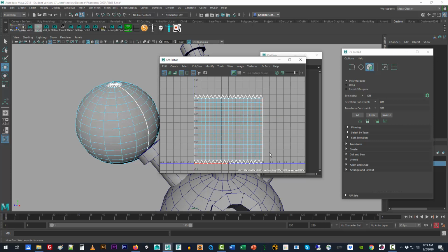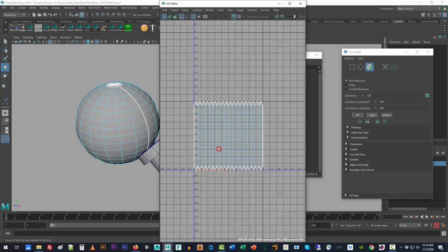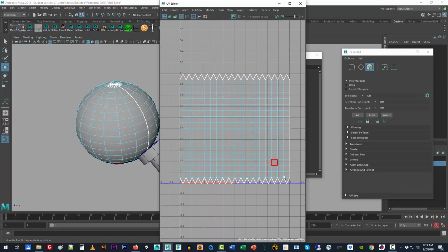One of them is whether or not we have the sphere laid out like a flat map, which is sort of the default of Maya, or whether we can take these spheres and actually make them into sort of orange slices in the UV sets to reflect the actual mass of how these are laid out. So the way that we do that is we tell Maya, first of all, we'd like to cut things because it needs to know if it's going to squeeze them in at the hemisphere, exactly where those cuts are. And Maya has a couple of ways of doing this.